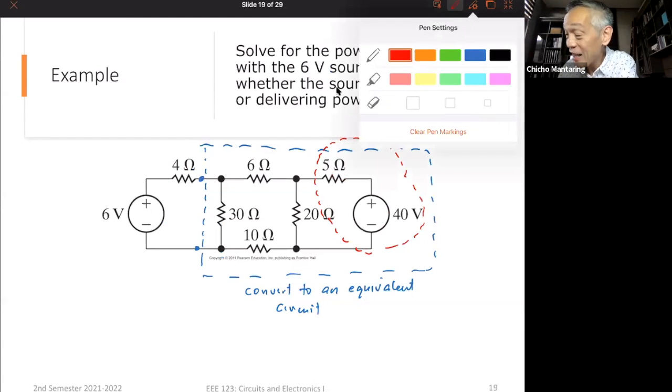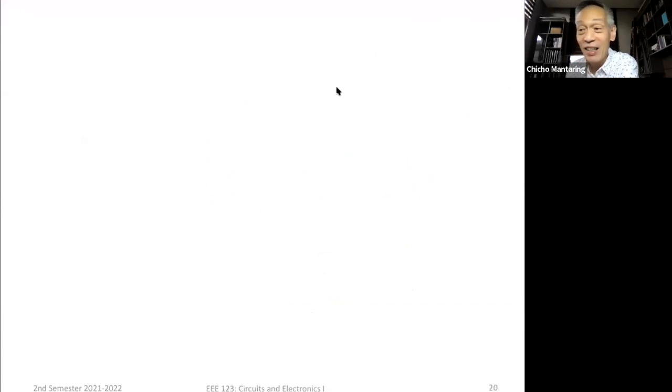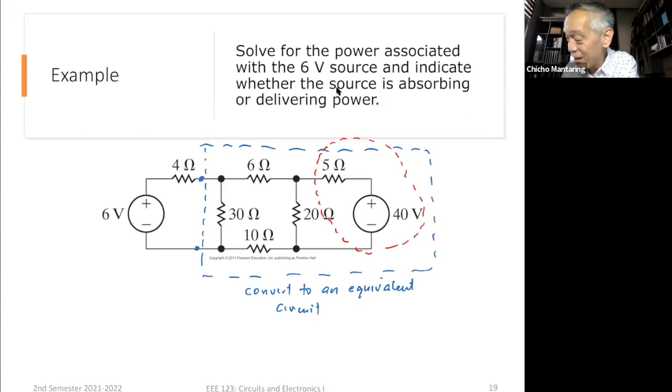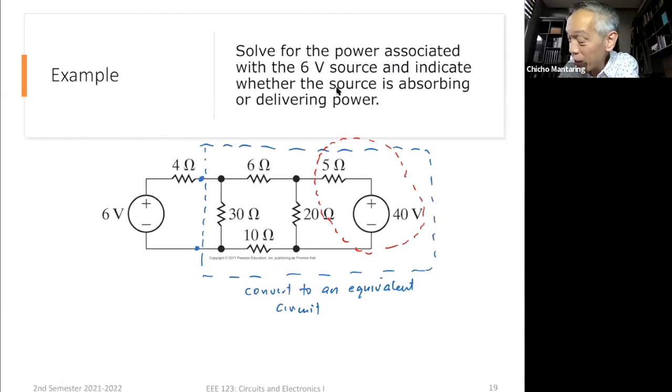Did you get that? Okay. So now, I will redraw that. That is now an 8 ampere. This way, 8 ampere. The current going from plus to minus. Then my resistance, previously in series, will now be in parallel. So this is going to be my 5 ohm. So what are these 2 points? These 2 points are this point and this point.